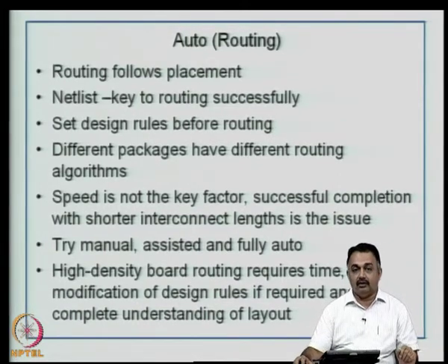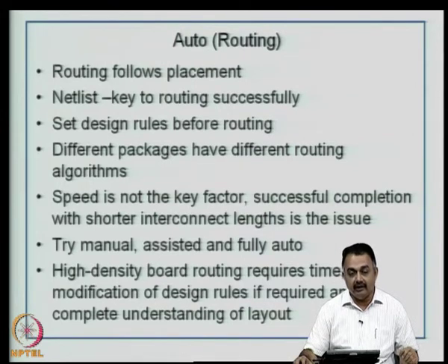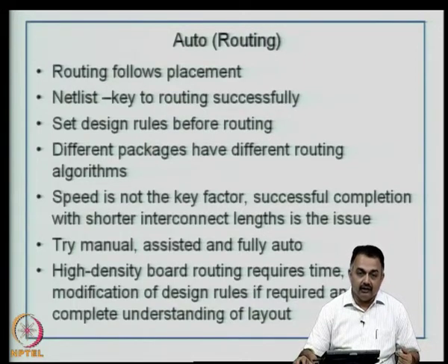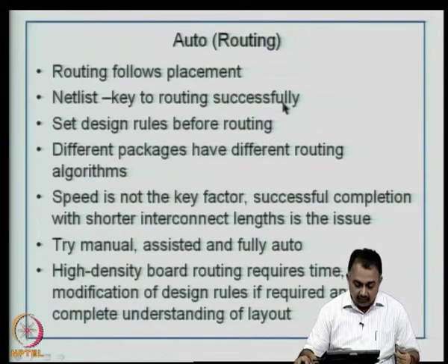You can also do auto routing or a combined assisted routing, but a typical designer will spend a lot of time using manual routing, because you understand exactly where the components are and what typically the net routes have to be in terms of line width and spacing and so on. So, routing follows placement. Netlist is a key to routing the board successfully.